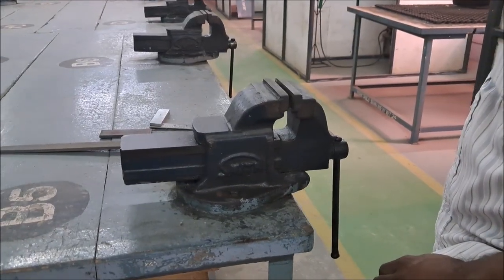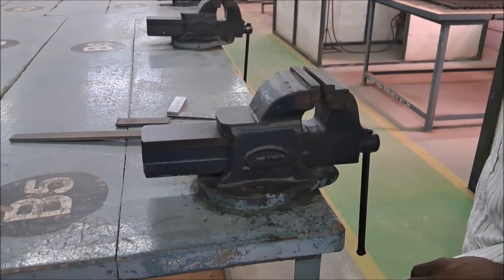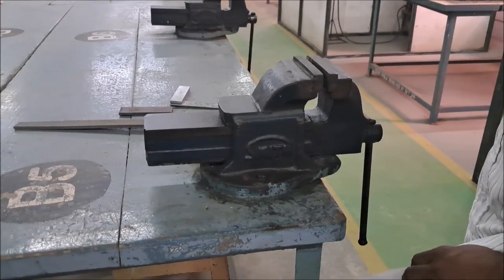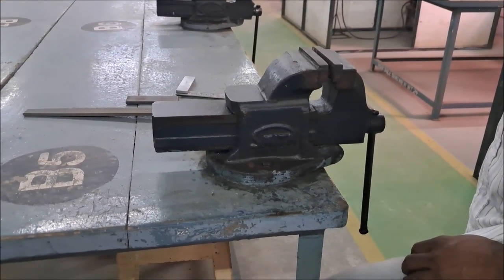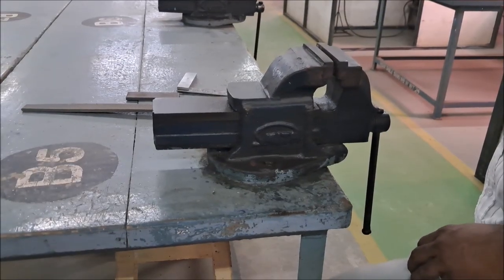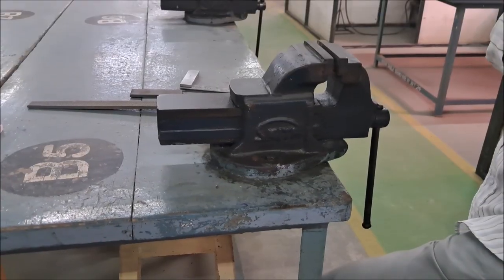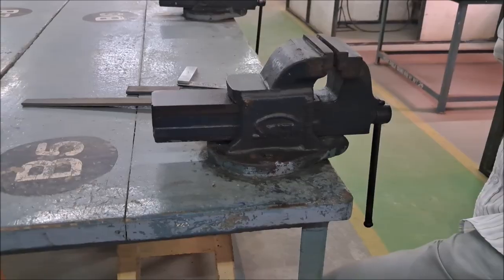Now we have already explained what is meant by butt joint, and the tools and materials required, all those things clearly. Now the working process, the working steps. What is the first sequence of operations? First edge preparation, tack welding, then chipping and cleaning. These are the sequences you have to follow to do the butt joint.